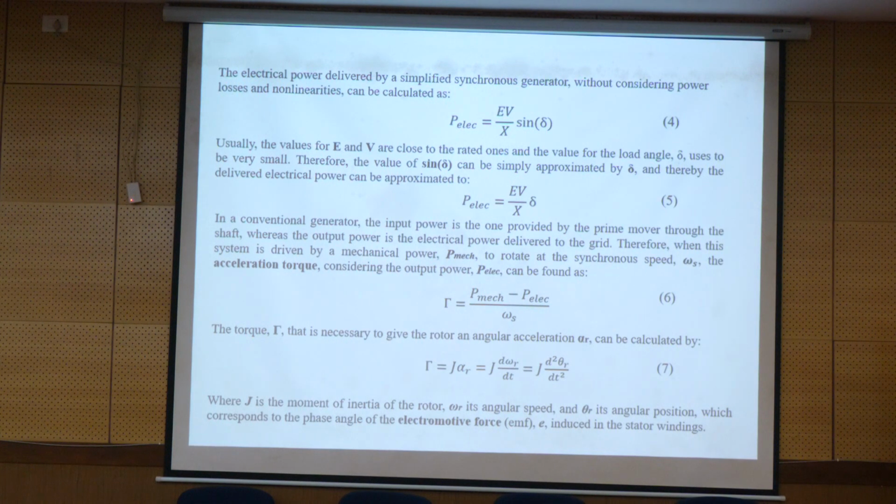Because there are two different parts. When you connect this rotor of the generator to the grid, it doesn't mean that they are aligned, because we don't have a PLL to consider in the control loop. In the converter we had one, but for the synchronous generator we don't know the position, so we cannot fix it based on that. So we start from zero, and then at some point we see that there is some difference between them. The speeds are at nominal value, so they are not too different from each other.